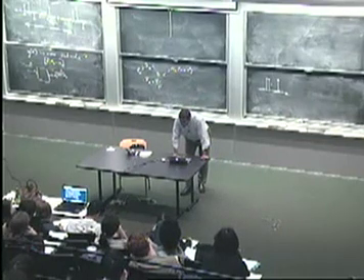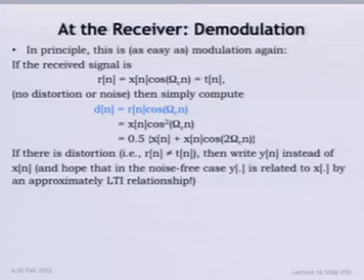Okay. So what happens at the receiver? We already saw this briefly at the end of lecture. If what you receive is what you transmit, in other words, if it's this signal, then extracting the x of n is easy. We said what you do is you basically do the same heterodyning again, right? You take the signal that comes in, multiplied by a cosine at the carrier frequency.